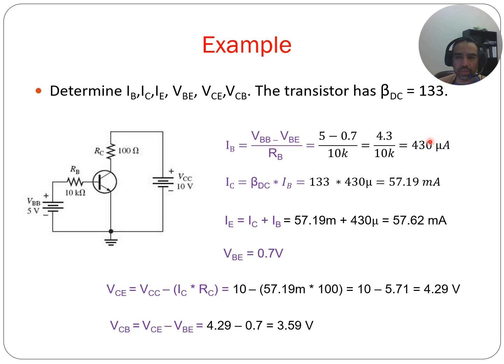If you had something like 1 milliamp, 2 milliamps, 3 milliamps on the base, you've done something wrong with your calculations, because the base takes a tiny, tiny amount of current. It doesn't need that much. The collector current, on the other hand, is going to be in milliamps. So you can calculate it as beta times the base current.